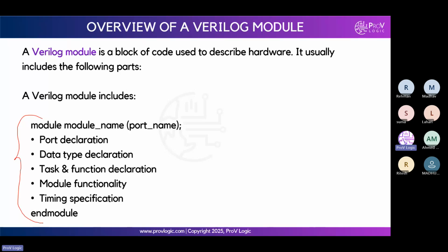Synthesis is nothing but design, writing the program, and if you put the program into the synthesis tool, we will get the circuit netlist. That process we call synthesis. If you do the verification, that means if you apply the test bench to the design, that process is called simulation, verifying the output. We already installed both tools, one for synthesis, one for simulation, right? So now we'll see what the syntax is.